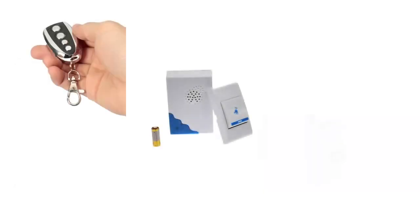car. You can also use these devices for more practical purposes, such as interfacing with existing commercial products such as remote keys, remote doorbells, sensors, and other smart appliances, which happen to operate on this frequency. Not all of them do, and not all of them have this encoding, but there's quite a few of them out there which do operate on this frequency and use ASK encoding.